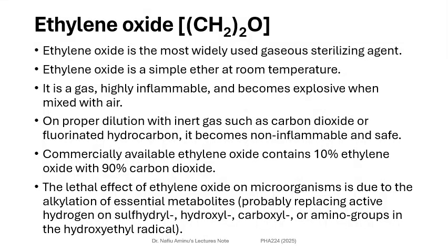This kind of sterilization agent has to be handled by experts that know what they are dealing with, because fire is one of the big disasters that must be prevented. It is a gas that is highly inflammable. It can easily catch fire if not handled properly. That's why proper dilution has to be made. Proper dilution with inert gas such as carbon dioxide or fluorinated hydrocarbon is necessary, and this dilution will lead to making it non-inflammable and safe to be used.